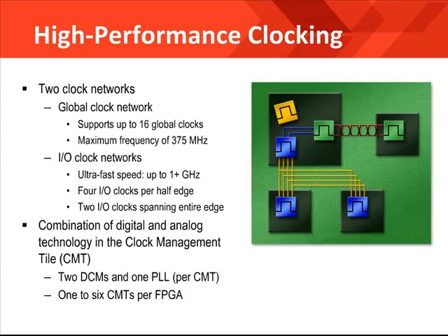That is, the DCMs are used to remove the input delay of a clock brought into the FPGA, as well as for clock generation. The PLL does not provide division capability, fine phase shifting, or complementary outputs. That is all accomplished with the DCM.